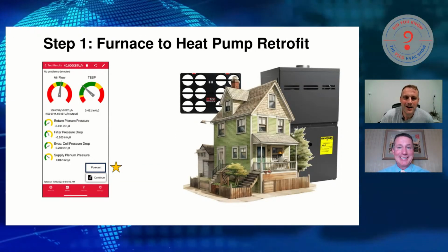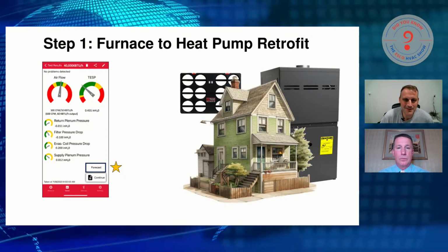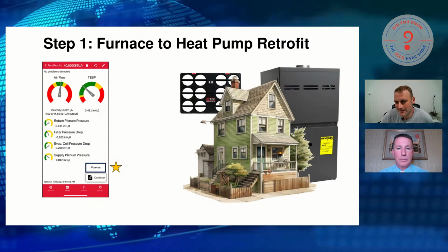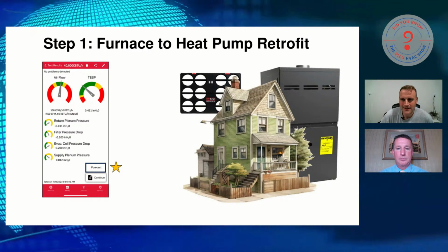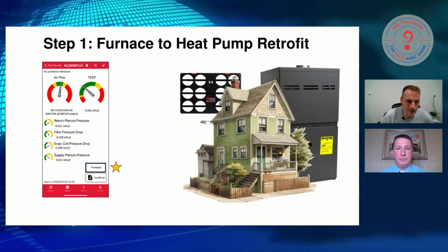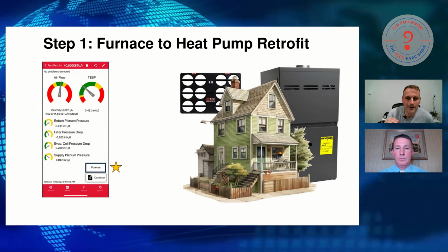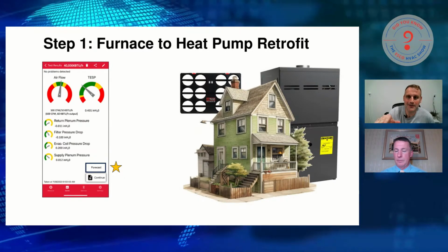So let's say we've got our grandmother's house right here, and she's got her furnace, right? And we want to know if we can put a heat pump in it. Let's say she doesn't have a ton of money, and she wants to go back with a heat pump. She wants to go for that credit. How do we know we can make the ductwork work? Exactly. That's a huge situation. So step one, you're going to run a TrueFlow test. Yep. And that's what this is showing on the left side of the screen.